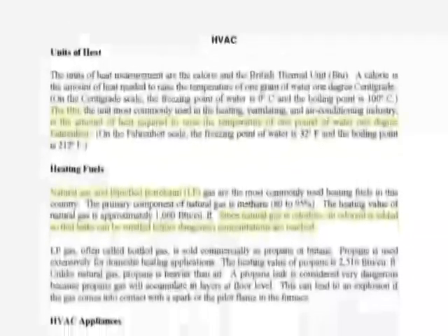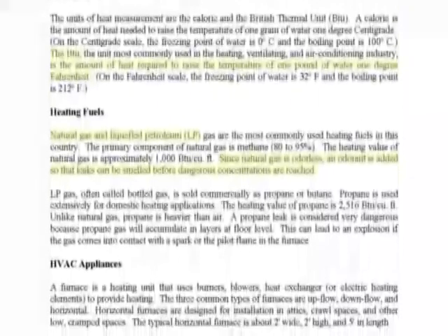The next paragraph speaks a bit about LP gas. I want you to read through that. And let's underline, unlike natural gas, this is the second or third sentence in there. Unlike natural gas, propane is heavier than air. A propane leak is considered very dangerous because propane gas will accumulate in layers at the floor level. Underline that sentence.